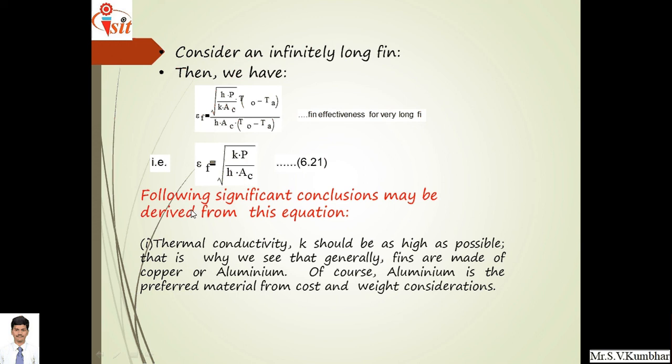Now there are significant conclusions we can make from this derivation. The thermal conductivity k should be as high as possible. That's why we see that generally fins are made up of copper or aluminum, and generally aluminum is preferred over copper because of its cost and weight consideration.